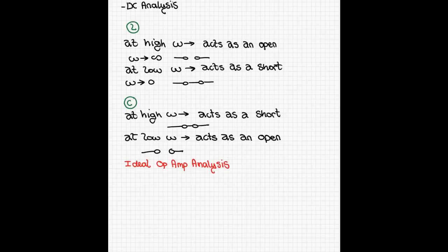Say we got an op-amp right here, positive terminal, negative terminal, then we get the output. One of the things that you should remember, this is VP, this is VN, is that for ideal op-amps, VP is equal to VN. The op-amp will try to do anything to keep the difference between these two terminals to 0, right, to keep them equal.